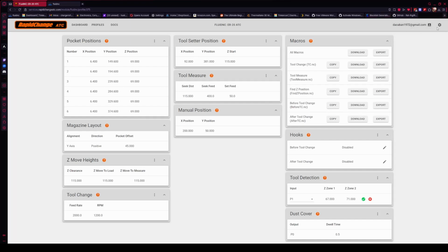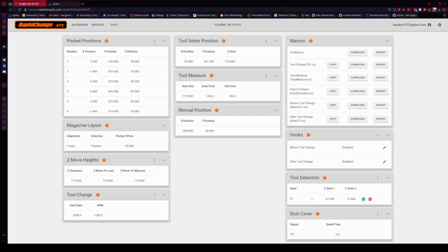So if I go over to the edit Z offsets, 42 is going to be my engage because it's a subtraction of the Z position and the infrared here. And that's how it ends up calculating that. And usually once it's set, it's a lot easier than it was in the past to set it up. You can fine tune it pretty easily, but that's all you have to do with that portion of setting up the Z.